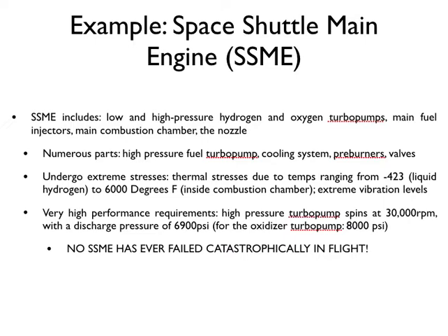The thermal stress due to the temperatures is pretty impressive on this thing. Temperature-wise, its mission ranges from negative 423 degrees all the way up to 6,000 degrees Fahrenheit. This is something that not many systems see. And if you think about reliability and really the root of it, it's driven by its environment, right? If the environment is stable, then there's not typically a whole lot of interesting stuff to analyze unless it's a really extreme environment. But the change in environment and also extreme environments themselves are really what drive most of the issues in the system.